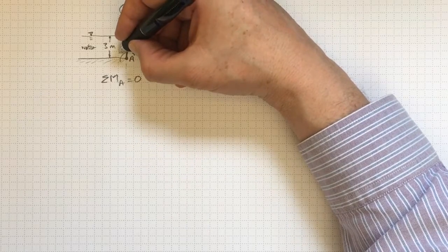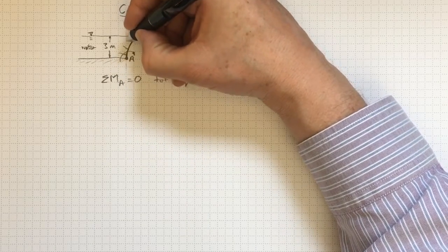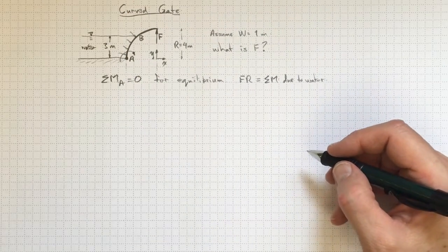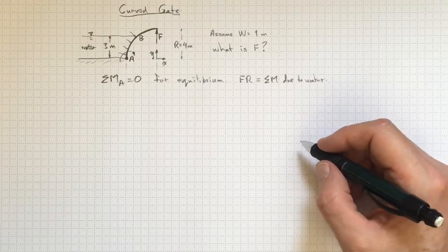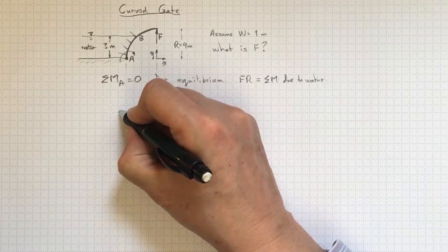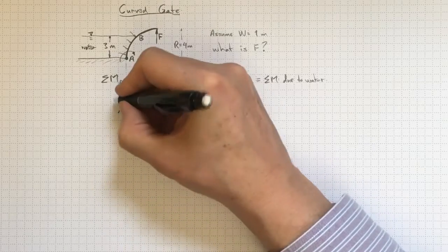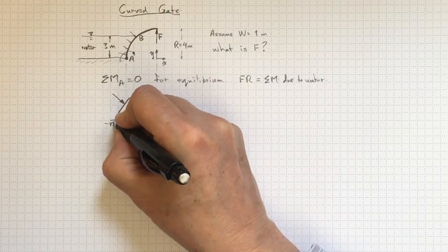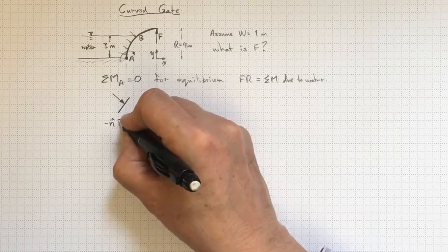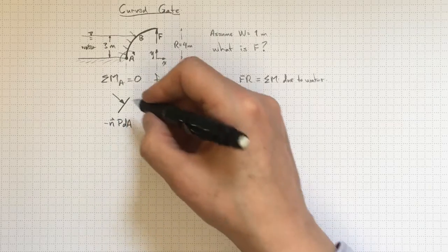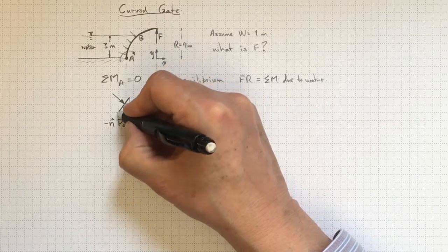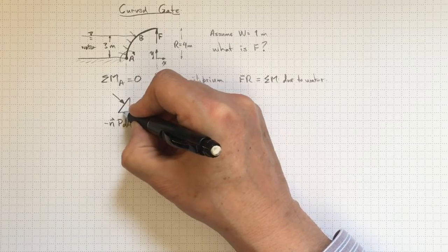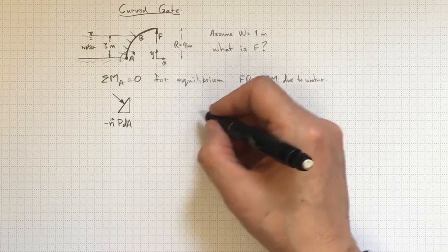Now, as we go around this curve, we're going to have pressure acting always perpendicular to the surface. So we're going to have to resolve this in terms of both X and Y components. If I took a little chunk of surface that might have that slope there, I've got a pressure force acting on it. It's going to be equal to negative n, where n is the unit normal vector, times p dA. I'll have to think about the projected areas in the X and Y directions to break that into component forces in X and Y to be able to manage my system a little more easily.